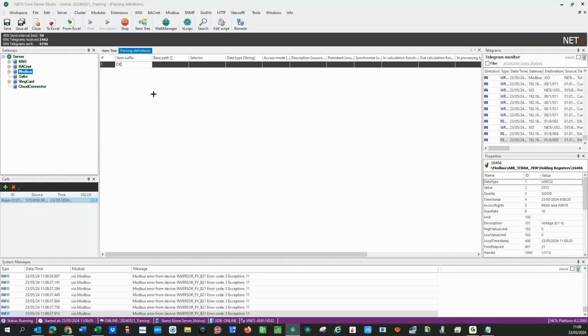And in the selector, we put the item, my specific item. But in this case, it's important to change this backslash to a double backslash, because for the parsing, it's an internal thing, the backslash has a specific meaning, so we need to have it doubled. Just something to remember.